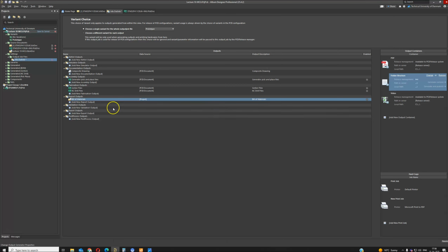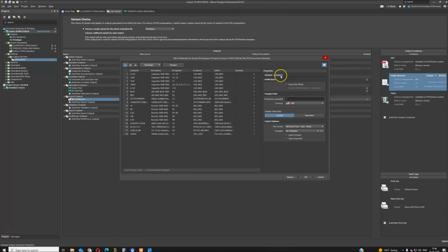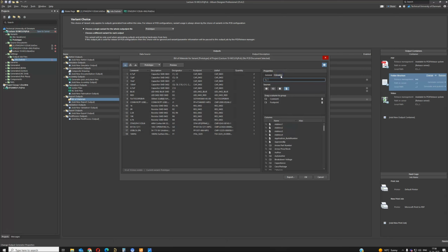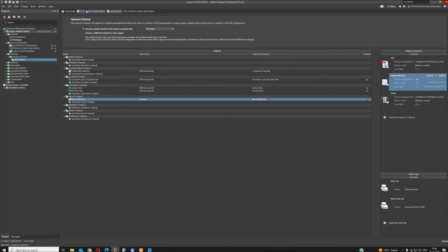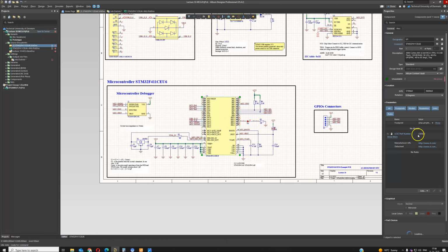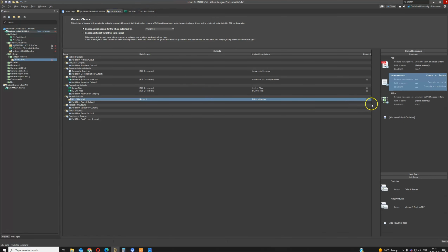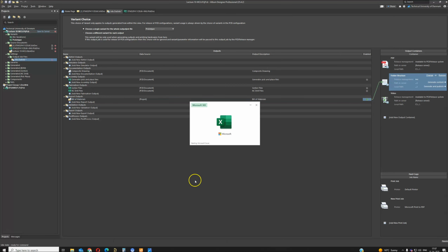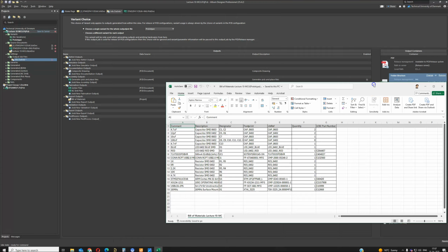Configure. So here we just need to add the LCSC part number. So this one, the one we were placing in the schematic, if you remember, we were selecting parts here, and then we select this number. So we want to add this number as well. Then I click here to the folder, generate. And that's how it looks basically.